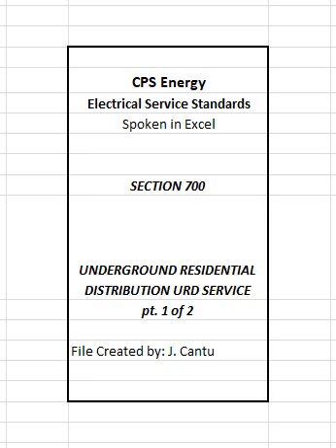704.2 Size of conduits. The size of service lateral conduits to residential buildings shall be as specified for the job by the CPS Energy customer service representative and will be based on length, number of bends, and the type and number of conductors that CPS Energy will install. Typically, all conduits from pad mount transformers to single position meter sockets shall be 3 inches unless otherwise specified by CPS Energy. Elbows at transformer end shall have a minimum radius of 30 inches and elbow at meter loop shall have a radius of 24 inches.